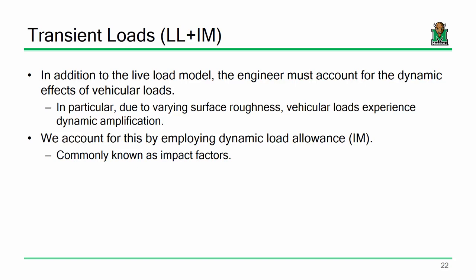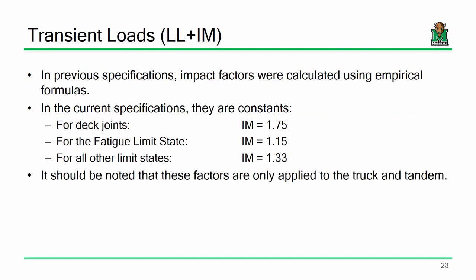So we take care of that through the use of what are called impact factors. That's why we've got this LL plus IM, the live load plus impact. That's what that means. All right. Most cases, we're going to use an impact factor of 1.33.